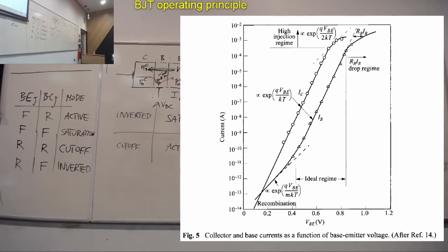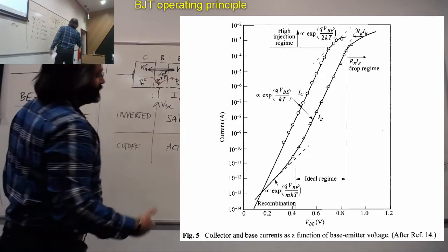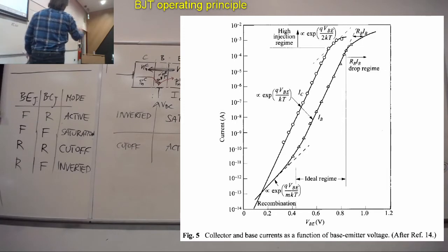So it is in this region that the transistor is active. Okay, if we come down here, we are switching off. VBE becomes too small, so the BE junction becomes effectively reverse biased or not conducting anymore anyway, and so the transistor also switches off. When there is too much current, IB is very large, which means effectively that VCE is dropping.